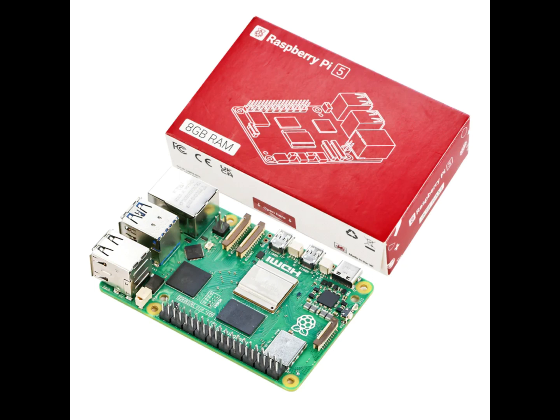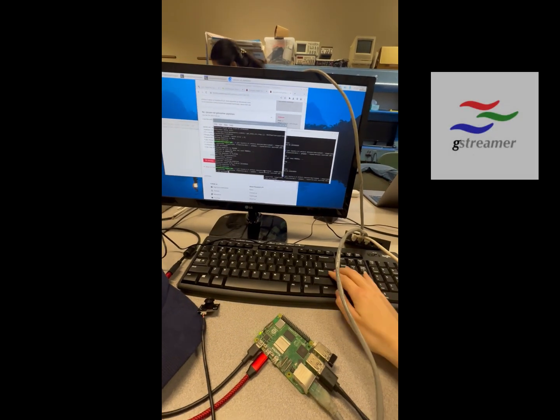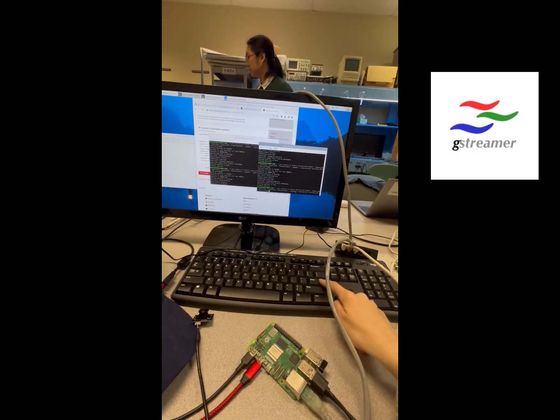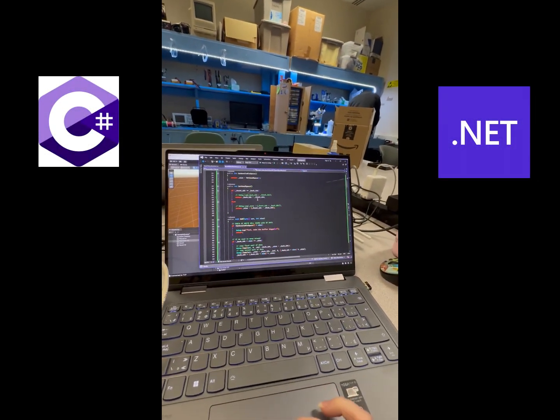In my module, I cover the video processing unit, which is done through the video game engine Unity on the base station. To begin, we first established the ability to receive one video camera data stream in Unity from the Raspberry Pi, which is hosting a TCP server over a Wi-Fi connection from the drone, onto the base station using the open source video pipeline GStreamer. We then scaled that to 4 camera streams to enable a more immersive view. Unity receives the stream over the air from the drone using a TCP socket connection in .NET, which is written in C# and bound to a Unity object.